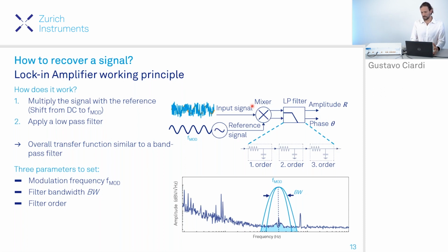This means that these low-pass filters are not actual RC filters with resistance and capacitance, but these are digital models of RC filters, with which our multiplied signal is processed in the digital way to obtain amplitude and phase of the signal.